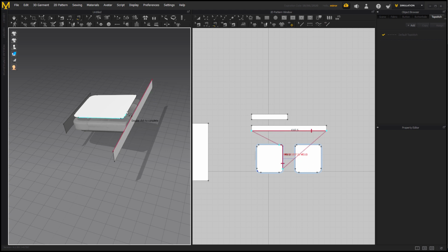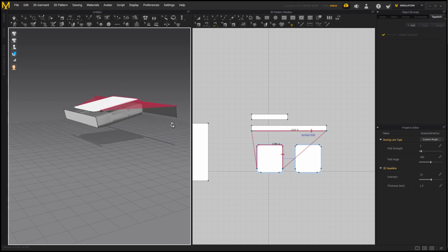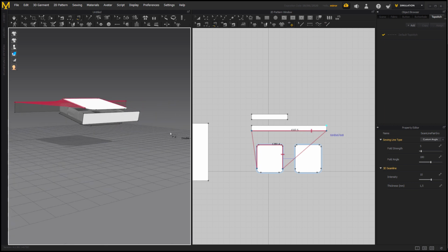you're happy. For longer sewing lines, single click along the route to make sure it sticks to your desired route. Then double click at the end destination. As soon as you have defined 2 lines, a bridge will appear that indicates where the flat patterns will be sewn.